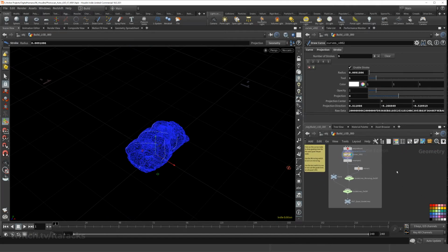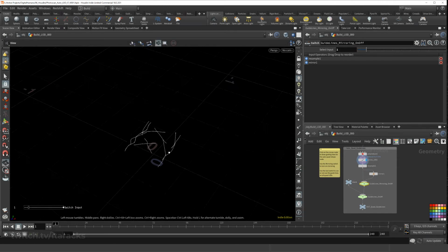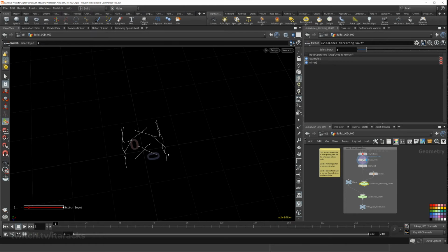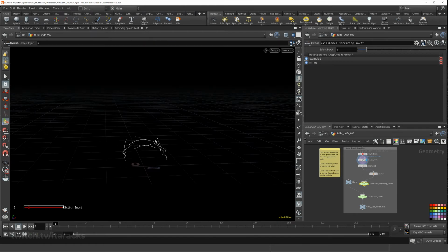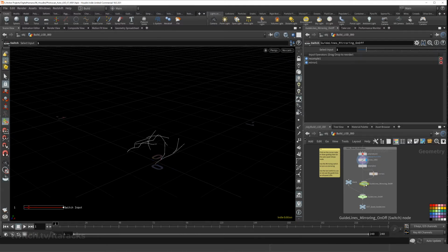And if you are doing something that is hard surface or something that you want to have mirrored, that's what this first switch is. It's just a way of turning it on. So because the model has been set to world 00, the mirroring will happen in this direction. So you can definitely mess with this node to pick which way you'll be mirroring. But if it's something organic like this, like a strudel, that doesn't apply. It's by default just left off. And also, if these spline guides are not something that you want to use, which by default they are not, you would just click them to 1 to turn this on and 0 to use a blank null.